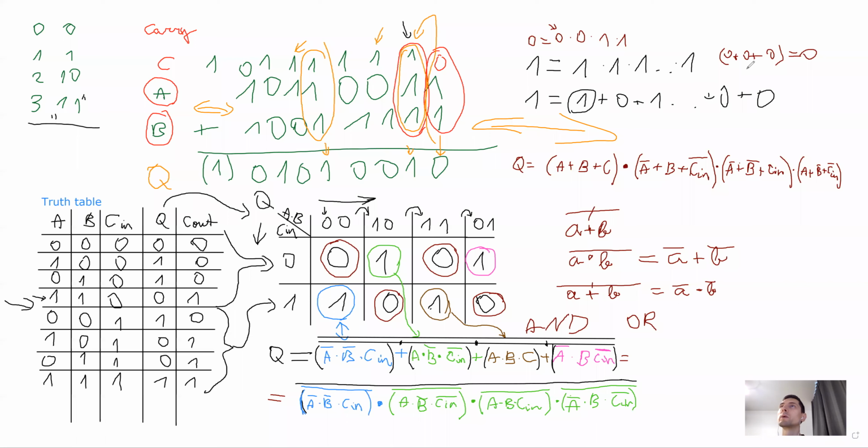So maybe there is something like this. This thing becomes NAND. And we can make it with just a NAND gate with 3 inputs. The next term is again A times B inverted times carry in inverted, and inverted multiplication with inversion at the end is called NAND. So again, the second thing we can also calculate using NAND. And the same applies for these things as well. And at the end, we have something times something times something times something inverted, which yields us another big NAND.